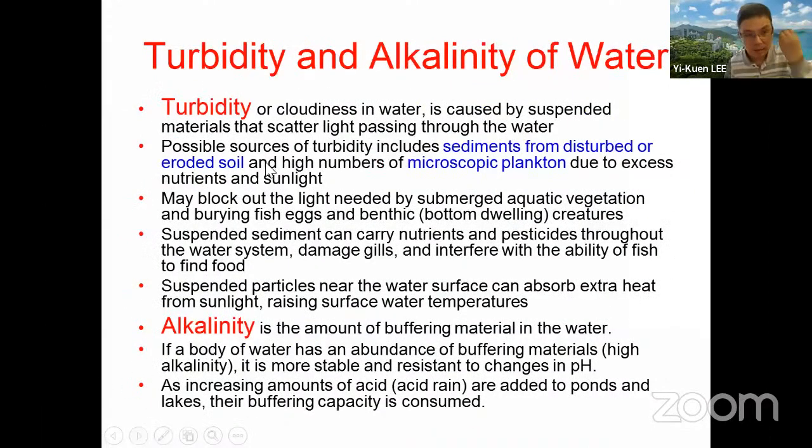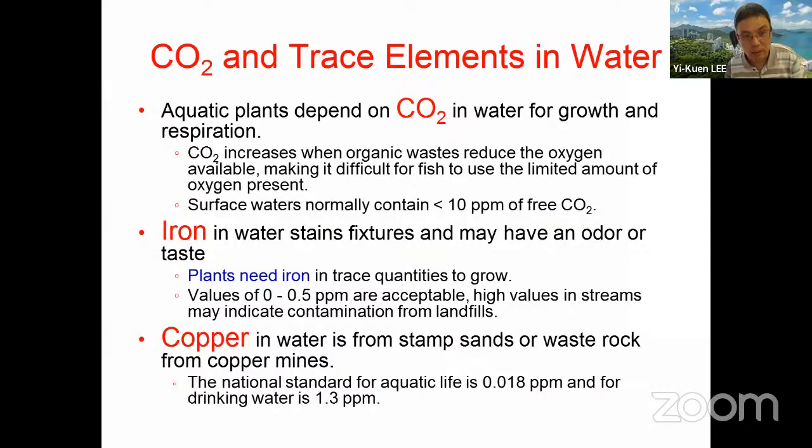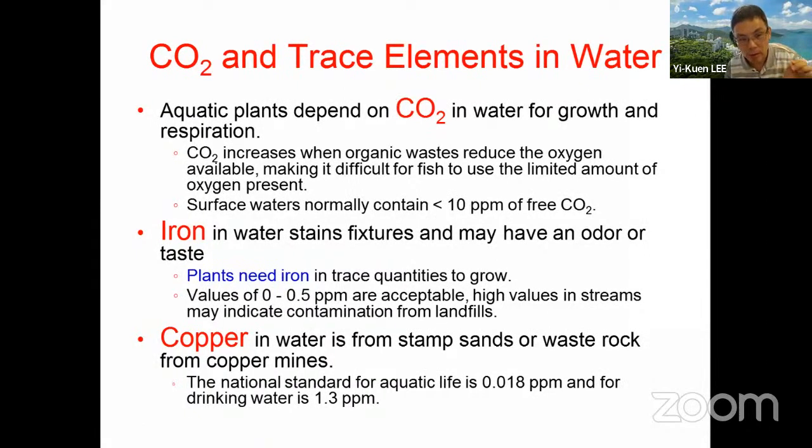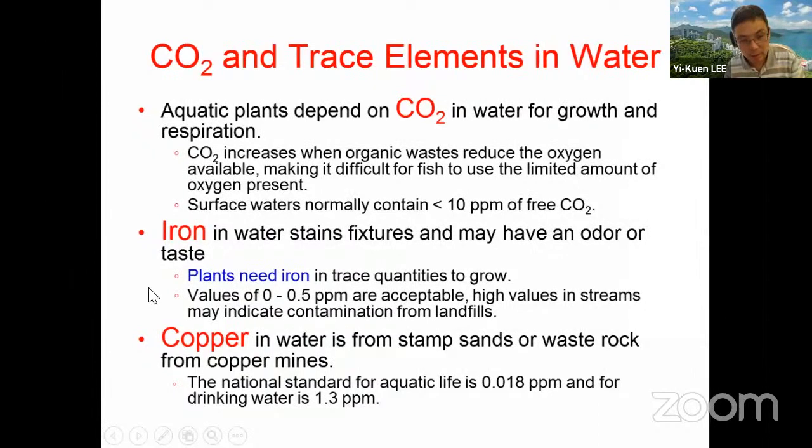And then in terms of some water, we look at the turbidity, right? If you have very dirty water. And then we have alkalinity, right? If there is a lot of special salt in the water, this is not good. And there is a series of ways we look at the chemicals in the water, such as CO2 and some trace elements like iron and copper.